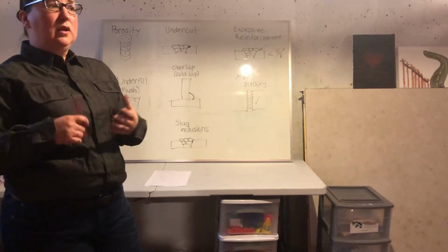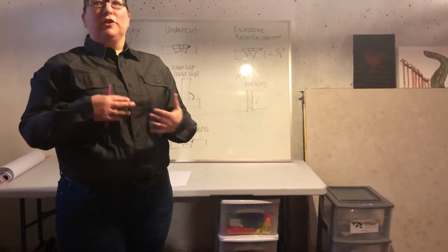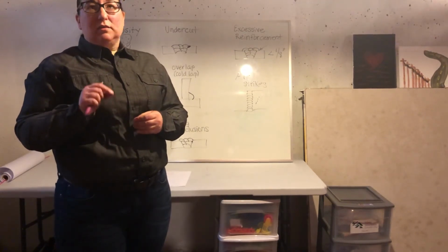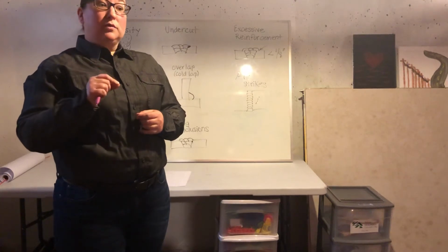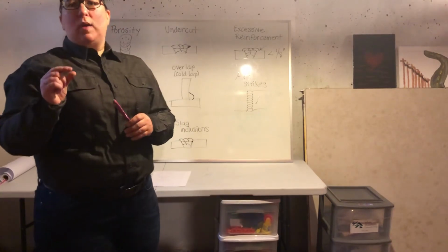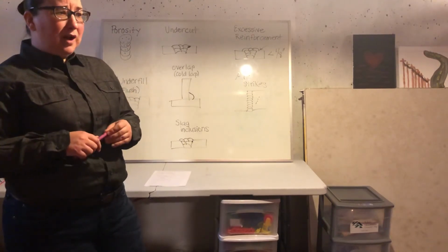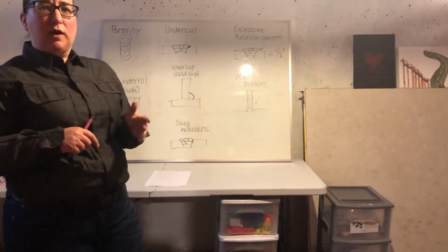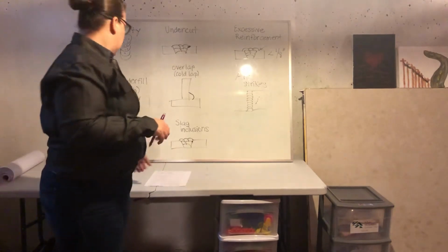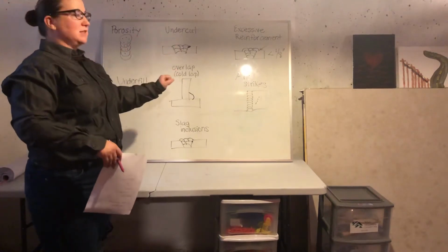The rule of thumb for arc length, and once again, different positions call for some exceptions to this, of course, is that we typically go off of the bare end of the metal. So if I'm using an 1/8" 7018 electrode, I would be about 1/8 of an inch away with that electrode from the base metal. That would be my arc length. And you can see it, it's that really bright glowing part at the end of your electrode. It's where that electricity is crossing. So those are all of your human error type things that contribute to these different types of discontinuities.